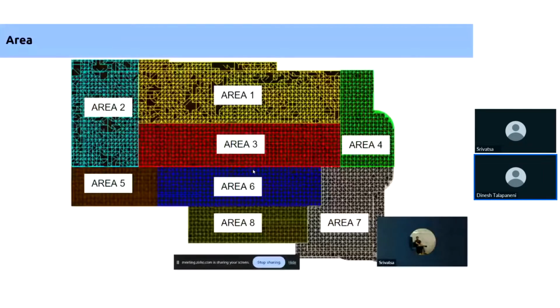This entire excavation has been divided into areas as per the contractor's execution plan, and the model has been built the way we have the schedule, divided into 8 areas. The side shorings have also been modeled, and all the nails that go into the soil for stability. This is the entire model of the excavation. When you remove the entire earthwork, this would be the side structure for stability.